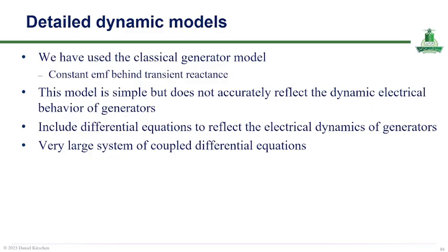So these equations are coupled with the mechanical swing equations, resulting in a much larger and more complex system of differential equations. So the use of detailed dynamic models allows more accurate simulation of generator responses during faults, swings, switching events, and other transient conditions.